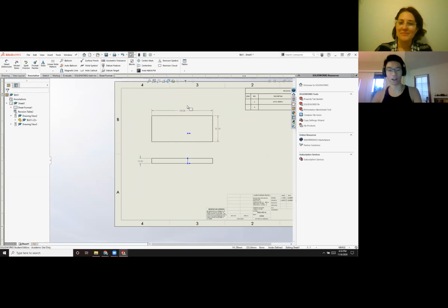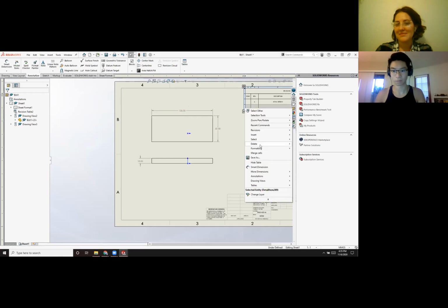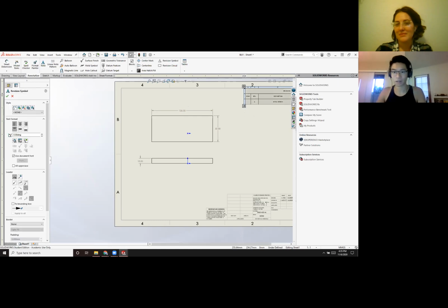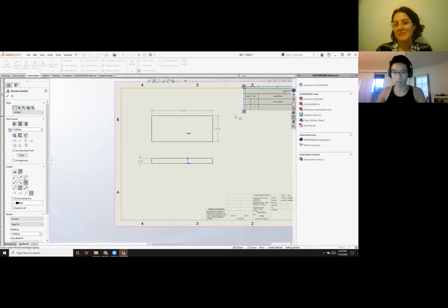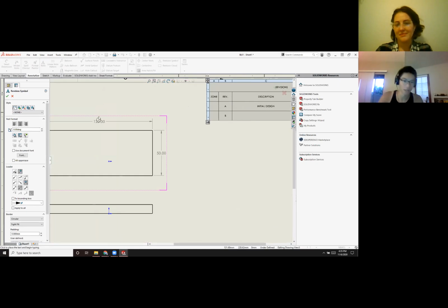And now you can see, I changed that from 110 to 120. So I'm going to go ahead and delete this column. Oops. Delete row. I'm going to delete the row so I can show you what I was initially intending to do. You can specify a new revision, essentially, a new revision B. And see this little circle here? This is your revision symbol. And it'll show up, B was changed.